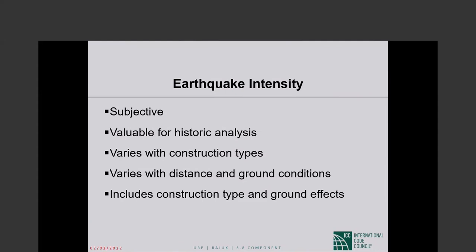Surprisingly often, I do not know. This is pretty much the rule rather than the exception. People, including sometimes journalists, will use the expression, this building was designed to withstand a magnitude 8 earthquake. That is a nonsensical sentence, doesn't mean anything. Absolutely nothing. Magnitude 8 earthquake where? If it is a magnitude 8 earthquake next door, it is one thing. If it is a magnitude 8 earthquake 1,000 miles away, then it can be a very flimsy structure.